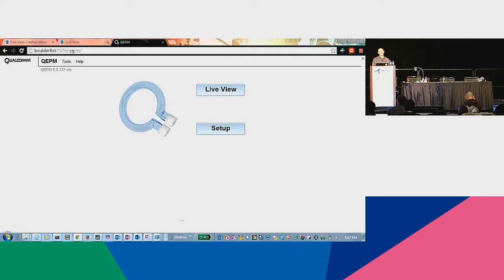The collection is done through an SPM card or an external card. We can monitor the board power coming up, and this is used internally at Qualcomm during our bring up as well. You don't have to have any software whatsoever running on this device in order to monitor power. It happens that this one is running Android.